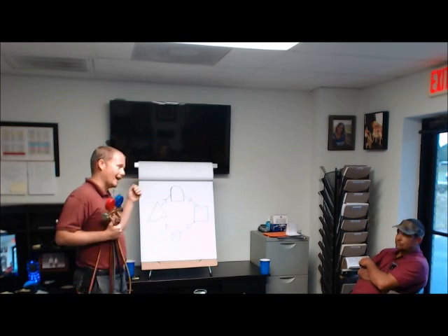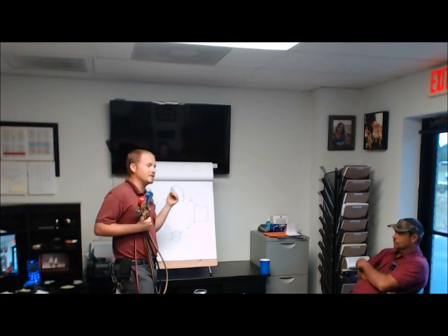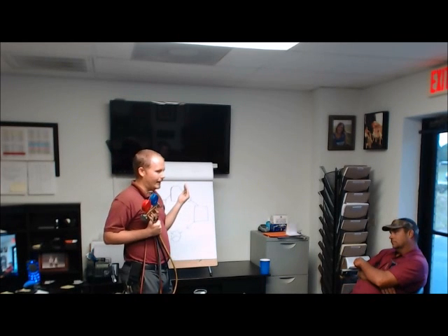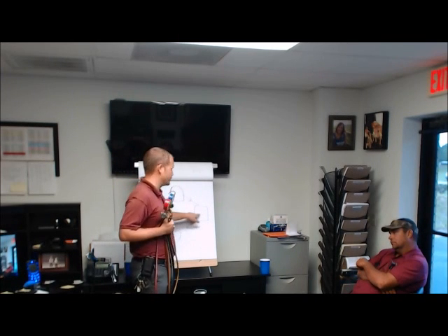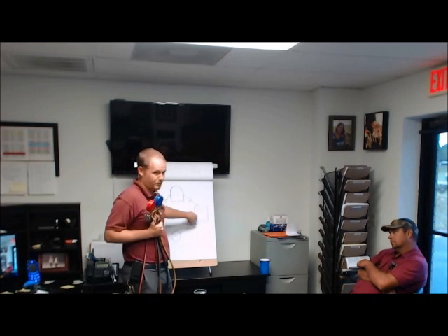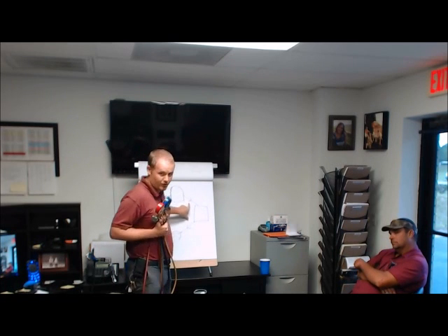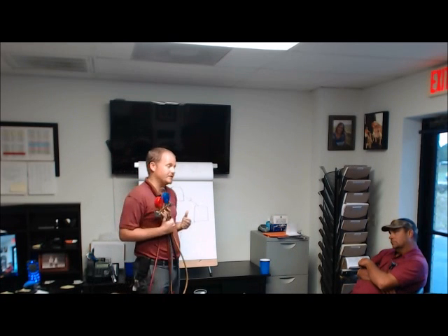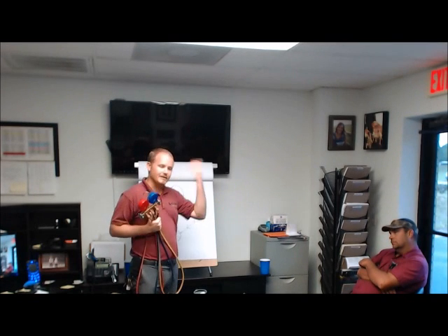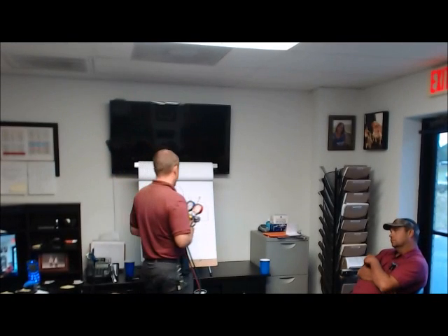They're actually not that much higher. It is higher, though. The only difference in pressure is actually the pressure drop through the condenser. It's just the same pressure state because you're forcing it together. It's that it's changed state, because now you're dissipating heat off of it and allowing it to condense down, settle down into a liquid state fully. Does that make sense? Okay.